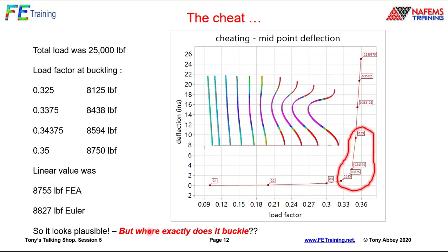But one of the questions now comes to mind is, well, where does that buckling actually occur? And that's one of the problems we have, that in a nonlinear buckling event, it isn't what we call a bifurcation, a rapid transition from one moment you have axial load and then you develop the lateral response. So this is the lateral response in terms of deflection shooting up in here. It's a little bit of a curve in here. So where do we nail that down? Where do we say that actually is? And that's a little bit difficult to actually decide.